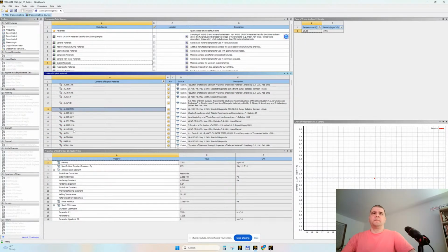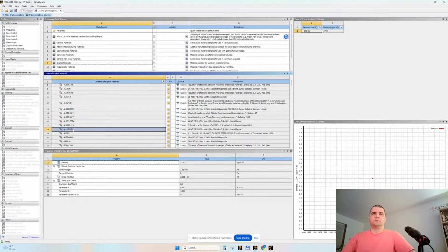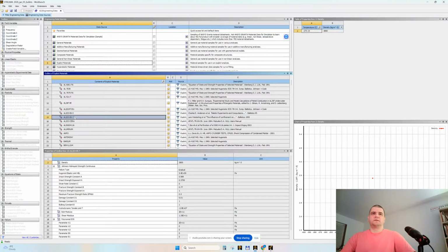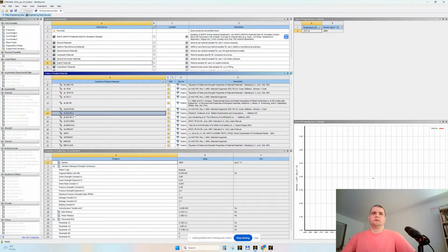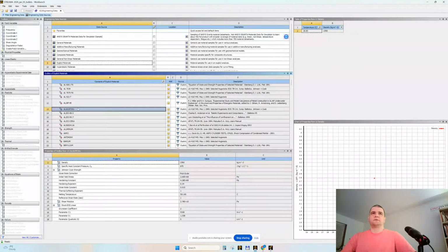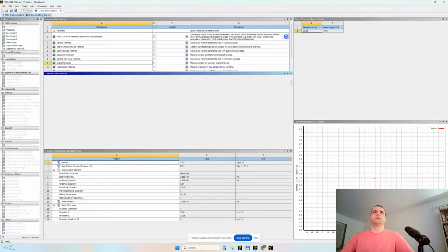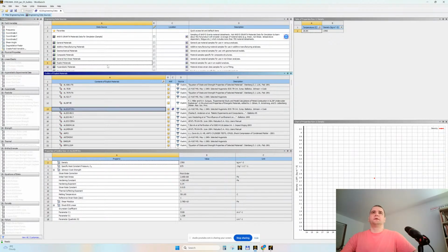I like this. What is aluminum? Bilinear isotropic hardening. So look here, we have plasticity, also a shock equation of state. Yeah. So at this moment, also Johnson-Holmquist strength continuous. Oh my God, it's very nice to have where to choose from. And let's keep three densities.